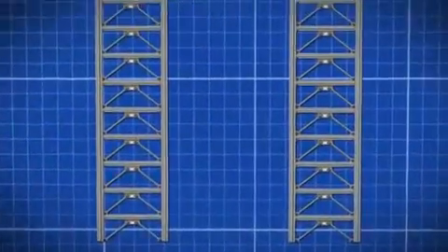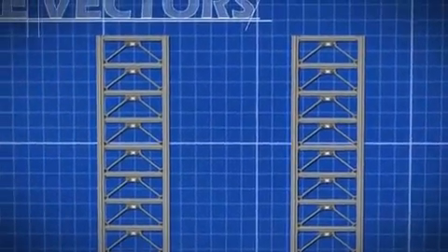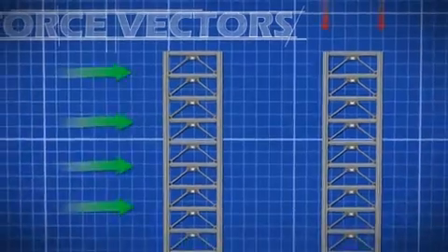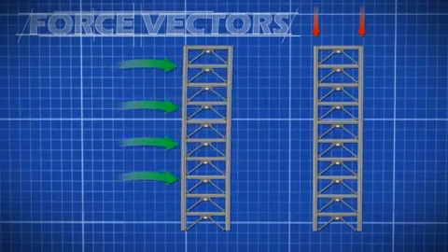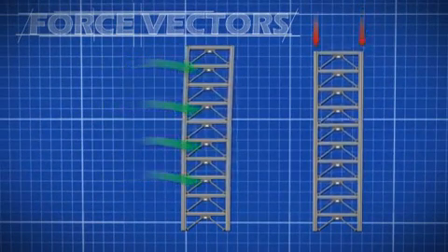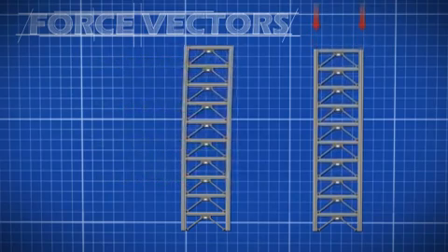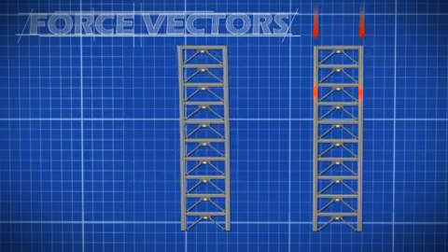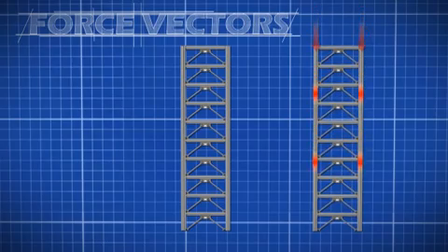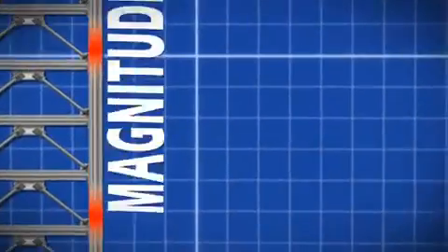Now that we've got the base of the site, let's think about the steel-braced core of our building. We need to consider the forces acting upon the building to know exactly how to design it. 2 of the major considerations for any tall building are the wind forces, being a lateral force, and the vertical loads, comprising of the self-weight of the building's materials, and any additional loads from people, chairs, and tables, to name a few. To understand the impact of these forces, we visually depict them using force vectors. These vectors represent the force's magnitude and direction.